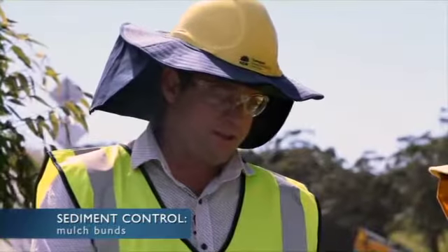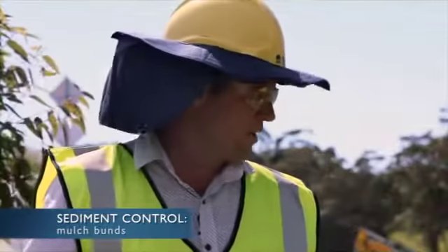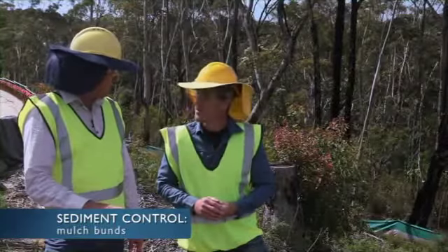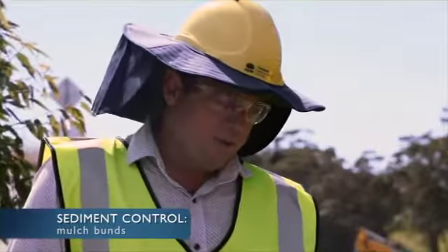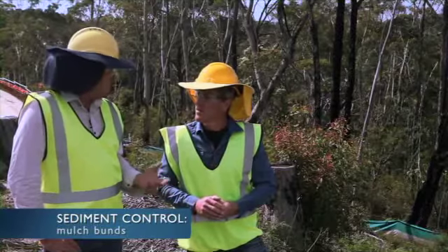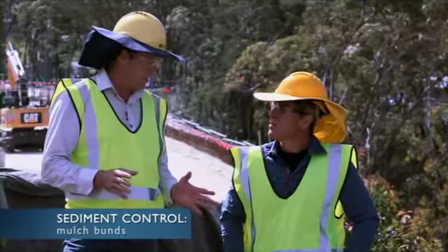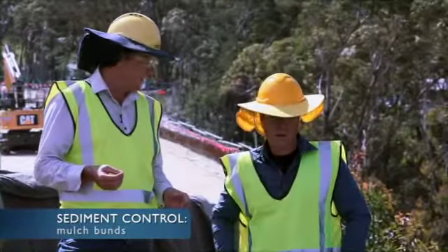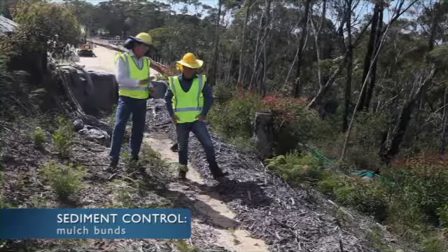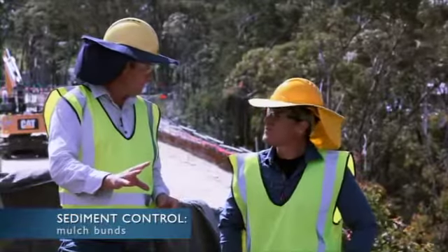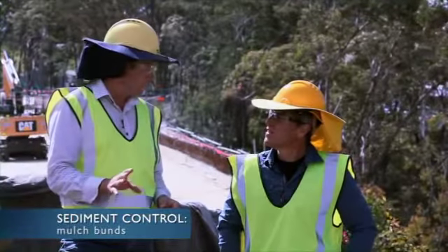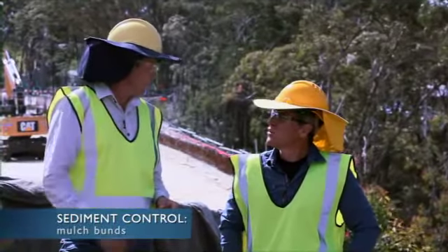One of the key considerations is they're designed to be used for sheet flow. They won't handle concentrated flows running through them. Also with the mulch, we've potentially got a problem with generation of tannins from that mulch. Now tannins is just a naturally occurring compound which makes the water dark, similar to tea. Right. So we don't want to over-apply mulch on our site, so we may get that problem. We also want to avoid using mulch from high tannin generating vegetation. Well, the use of mulch is a simple, economic, natural way of controlling sediment.